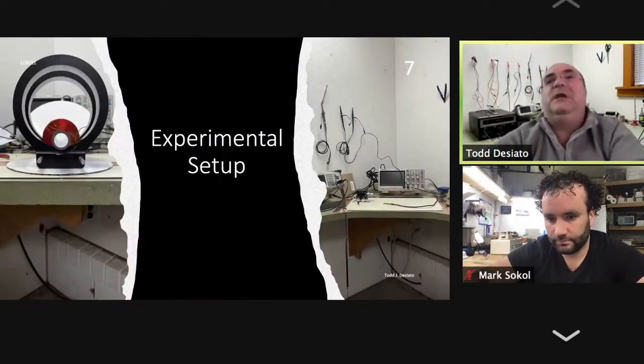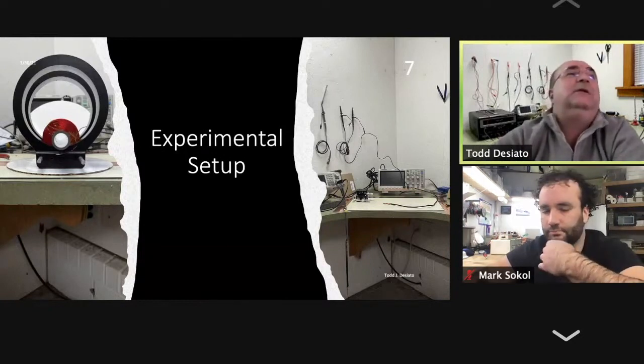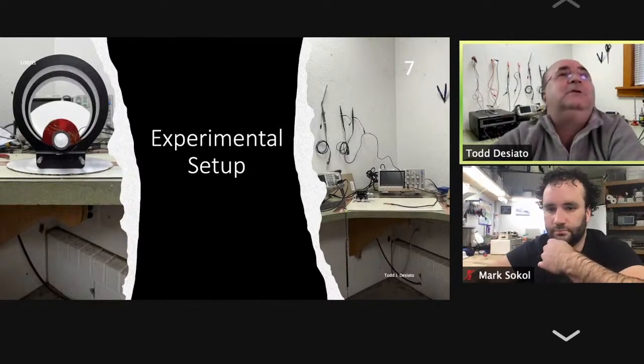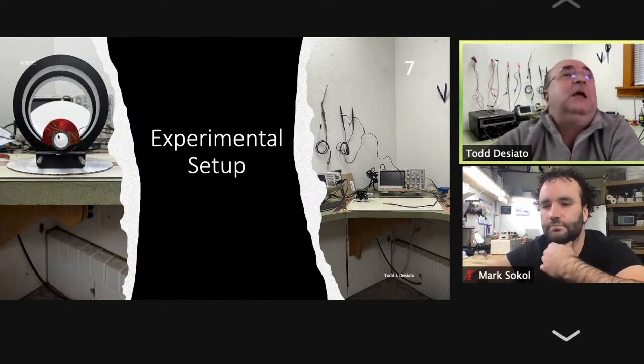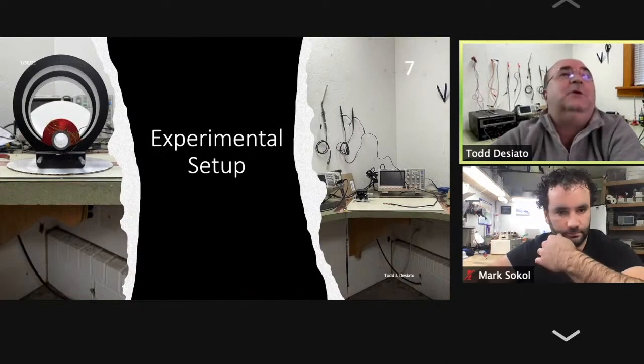So this is my little lab bench over here, and this is my setup, or the initial part of this setup. I have a pair of Helmholtz coils here, 44 turns. They could generate a field of up to 300 Gauss. And then I have a 9 millihenry coil here that is actually wound in the same direction as the Helmholtz coils, so that I can create a gradient in here.